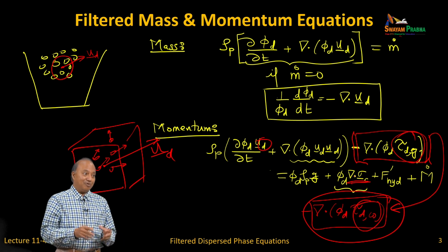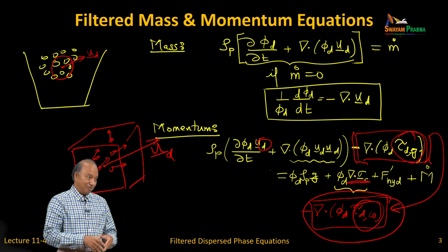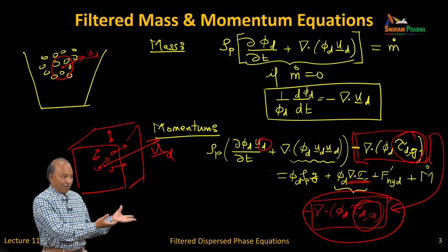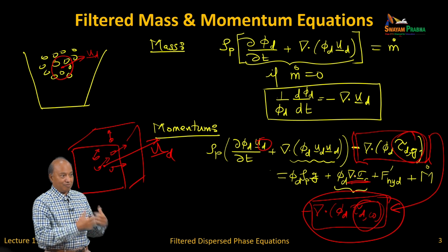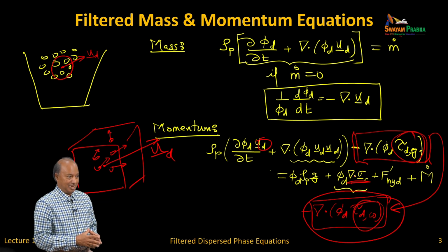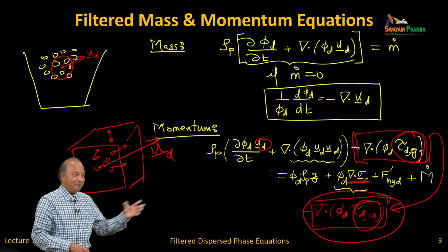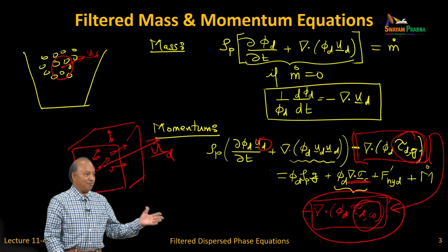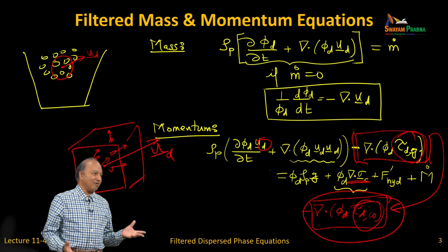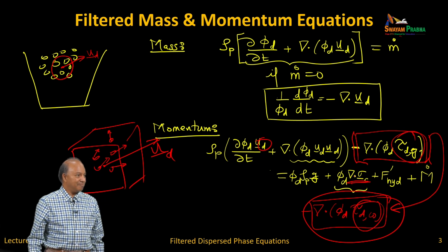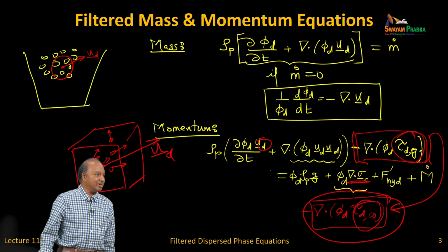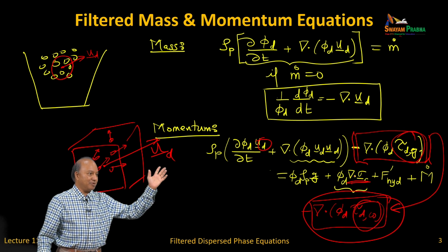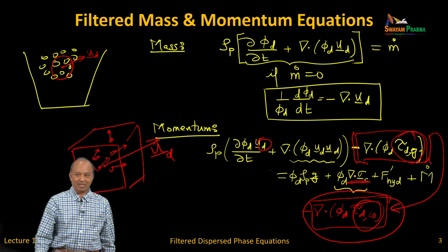We are not talking about the perturbation flow. We are saying here is the macro scale flow, its stress is sigma c, part of it goes to the fluid and part of it goes to the particles, and the proportion depends on volume fraction. That is all it says. There is no modeling needed, that sigma c is what you have computed earlier in the gas phase.